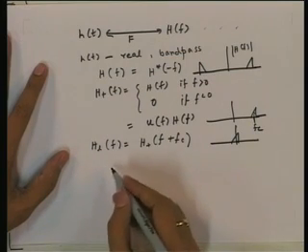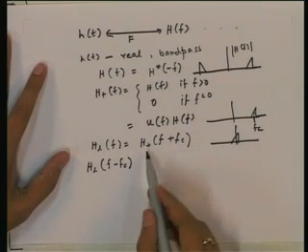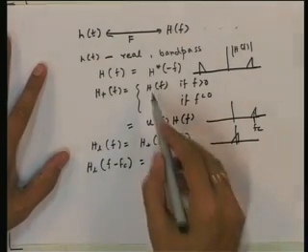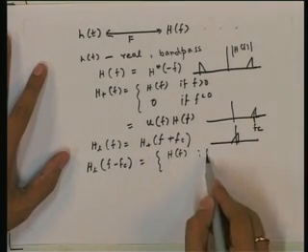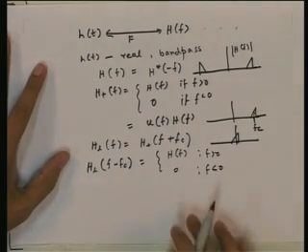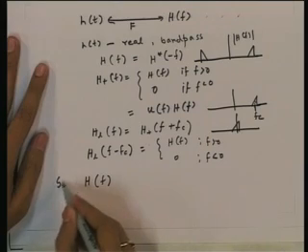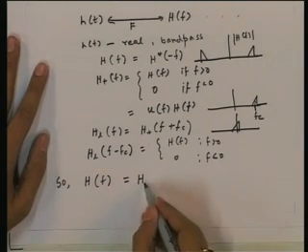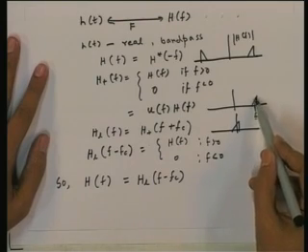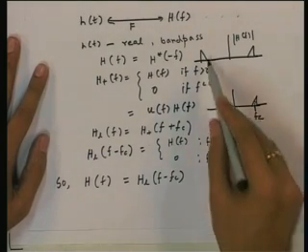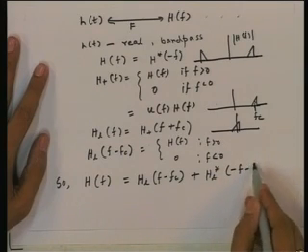Now in terms of H_L(f), what is H_L(f minus fc)? It is basically H plus of f. So H plus of f can be written as H(f) for f greater than 0 and 0 for f less than 0. So H(f) is H_L(f minus fc), which is basically H plus of f. If you add this with the negative part of it, which we have removed, that part we can get by taking H_L star of minus f minus fc.